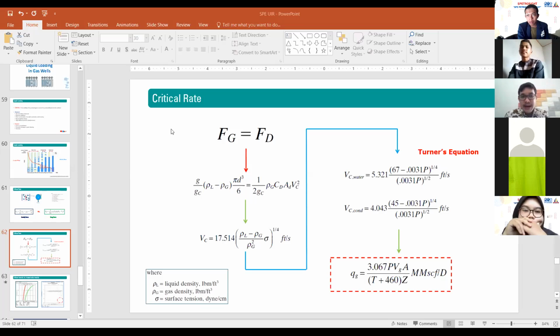So actually, we can do many things with IoT, with artificial intelligence, with machine learning. For gas reservoirs in particular, one of the things that can be done with IoT is to predict whether or not you will load up. If you have a gauge on your wellhead, you can measure the flow rate and the temperature, and on the station, on your test separator, you also have monitoring components or gauge meters, and all of them record the data continuously and send it to the computer at your headquarters.